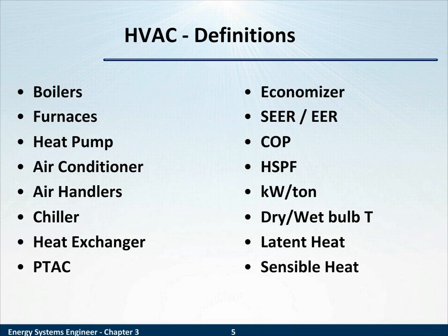Sensible heat, think of sensible, sensation, sensing. That's a change in temperature. Sensible heat is the heat that changes the temperature of a thing. Latent heat is after the temperature has been changed and it begins this phase change from liquid to gas, from solid to liquid. Latent heat involves the change of phase.